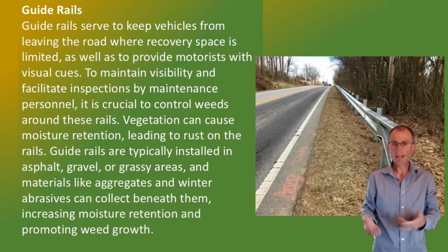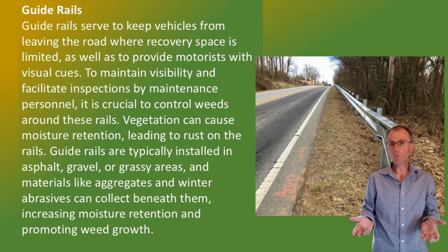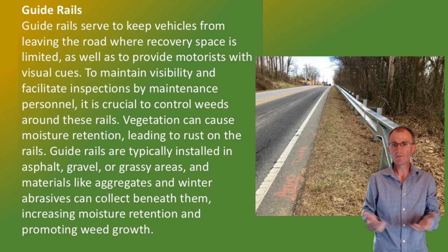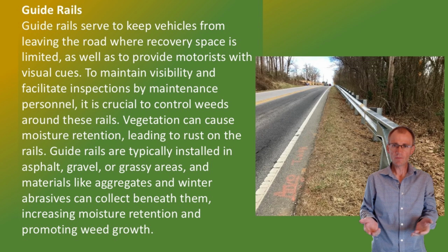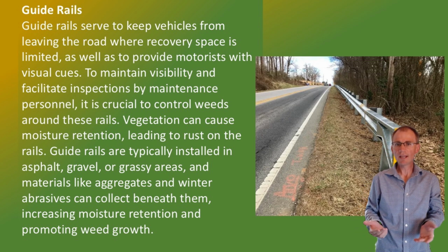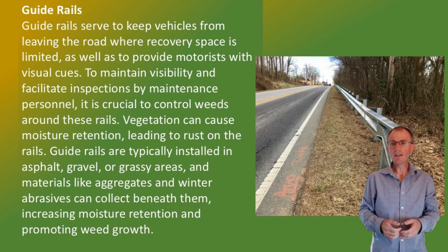Guide rails. Guide rails serve to keep vehicles from leaving the road where recovery space is limited, as well as to provide motorists with visual cues. To maintain visibility and facilitate inspections by maintenance personnel, it is crucial to control weeds around these rails. Vegetation can cause moisture retention, leading to rust on the rails.